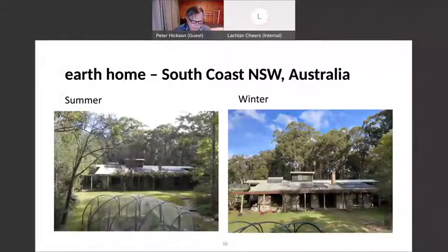My 28-year-old mud brick home is an older example of passive low energy earth architecture. It relies on simple passive solar design for cooling and heating. The heating is supplemented in winter by a solar space heater and wood heater. It is naturally ventilated and has 4.5 kilowatt PVs and a solar hot water system fitted. Earth from the site, timber products and recycled materials like the fired bricks and brick pavers help reduce embodied energy.